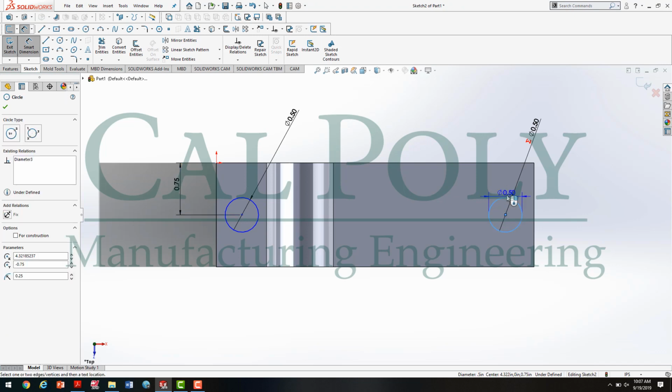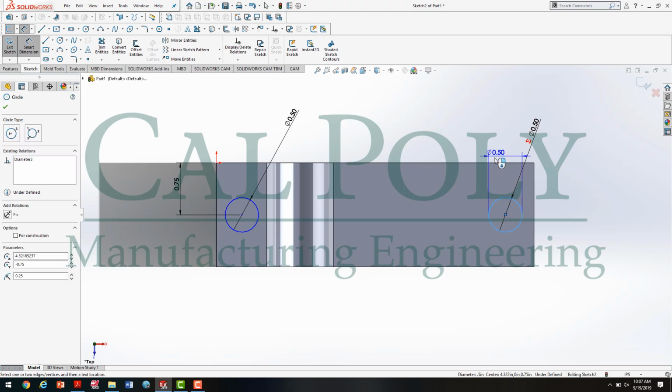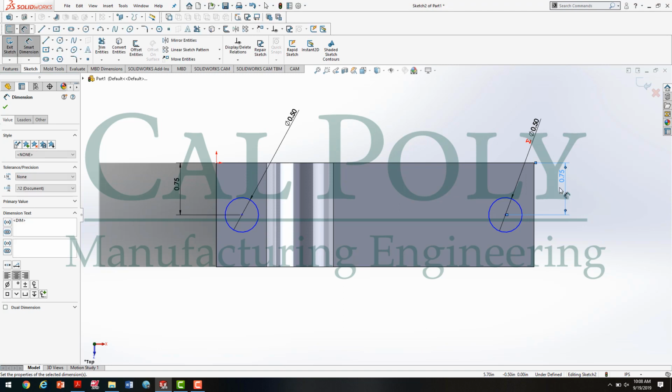You click on the edge of the circle, edge of the part, edge of the circle, edge of the part, drag out, and this one's already at 0.75. But let's say we wanted it to do math, we could go ahead and do 1.5 divided by 2, enter, which is exactly the same as it already had, 0.75.